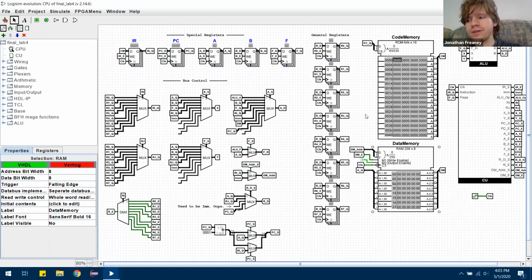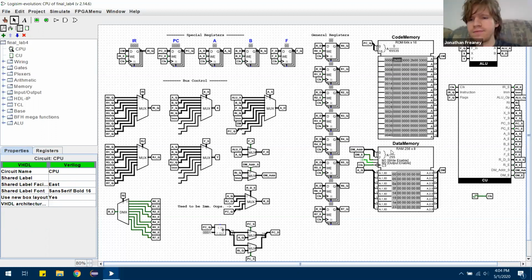This is actually, I think, the term, if I remember right, Harvard hardware architecture. Yeah, if you have separate code memory and data memory, that's what we have. For instance, the von Neumann architecture at Princeton. And you have a big address space for your code, which is good. And presumably you don't need that much data space for whatever you're doing. No, theoretically you shouldn't.